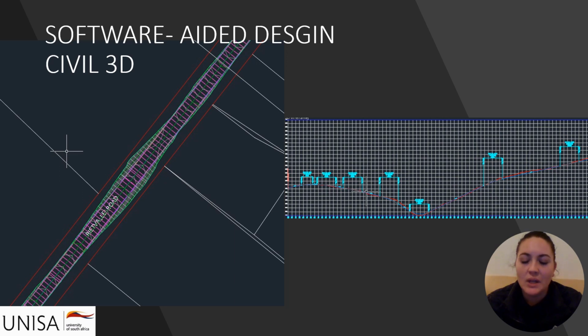Okay, next sample lines are created. This will then help obtain the cross-sectional and longitudinal information. This will give a visual representation of where the design level is in cut or fill compared to the natural ground level. I also use the corridors to calculate and obtain the volume report. This aids in producing the mass haul diagram as requested in the brief.